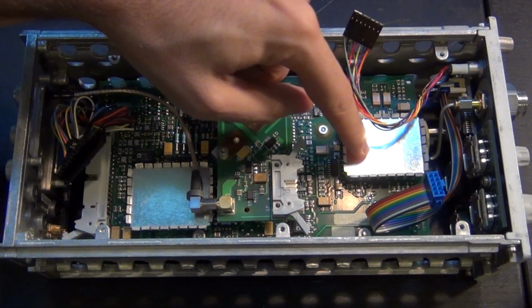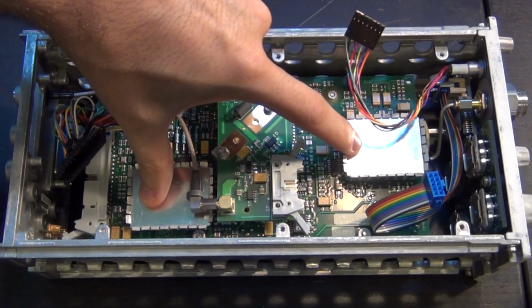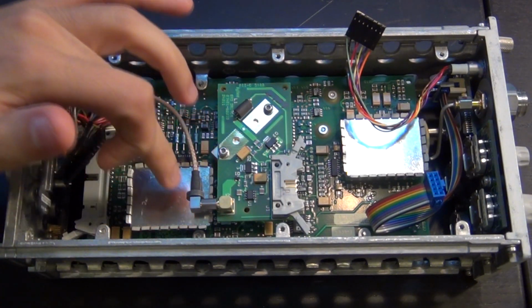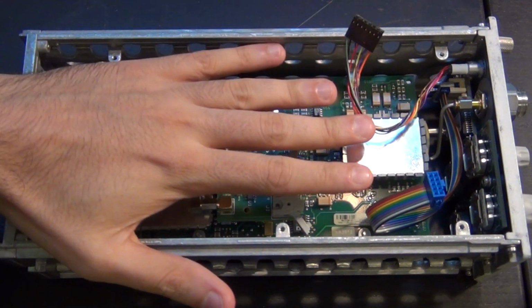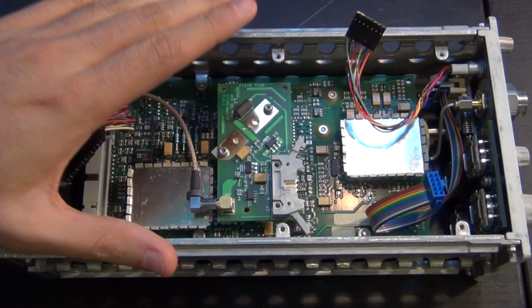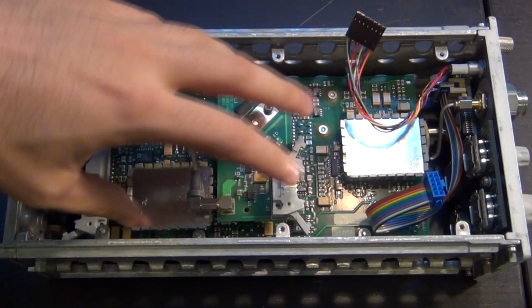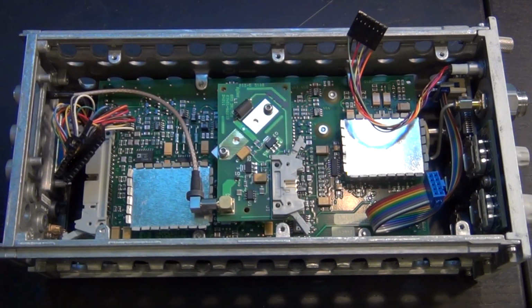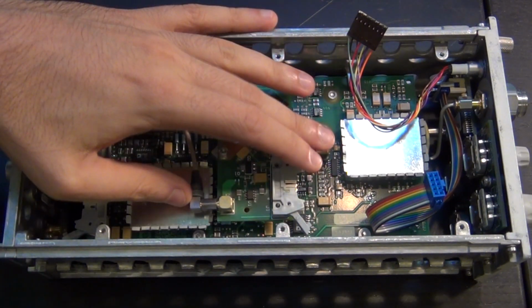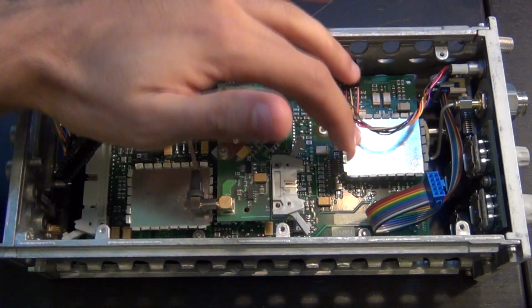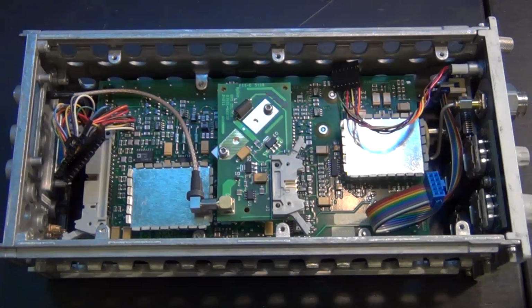And these two cages that you see here are obviously the back of the sampler. So the analog IF signal has to have very high integrity. Remember, that signal has to reach the A to D converters, which are not in this module. They're back in the mainframe. They need to be digitized with very high resolution. They need to keep their integrity so that they can be sent right out into the DCA mainframe to be digitized. So this is filtering, perhaps. I'm sure there's some filtering component. We'll take it off, preserving and amplifying it, to make sure it has good SNR before it leaves the module.